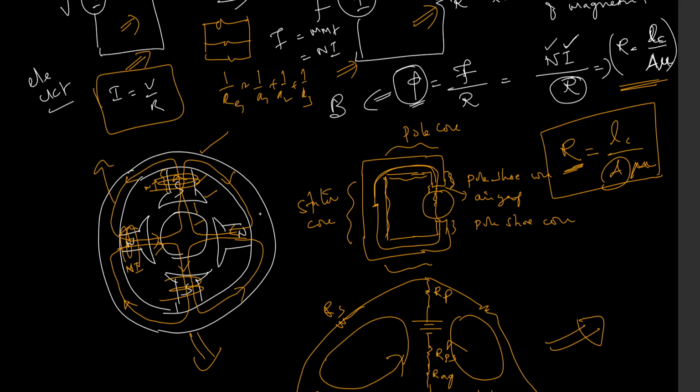So that is why we go for the third method, the compensating winding. In compensating winding, armature reaction is completely eliminated, but it also has a drawback, that it cannot address the L di by dt voltages. So that is why along with compensating winding we will be using interpoles, so that it addresses both problems, armature reaction as well as the L di by dt voltages. And we have also seen some basic principles regarding the magnetic fields in the machine and how to go about fixing the various parameters in the design aspect. I'll stop here. Thank you.